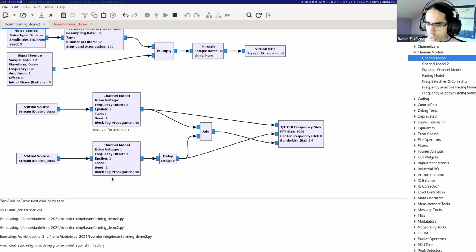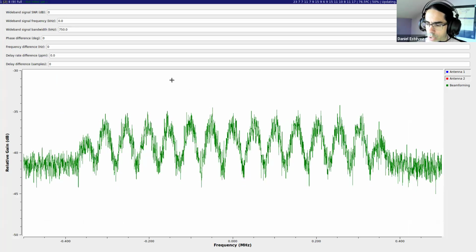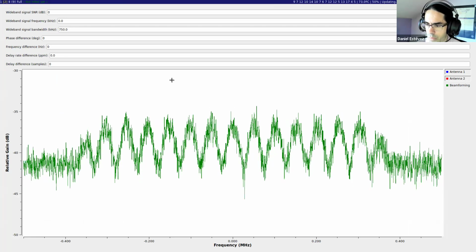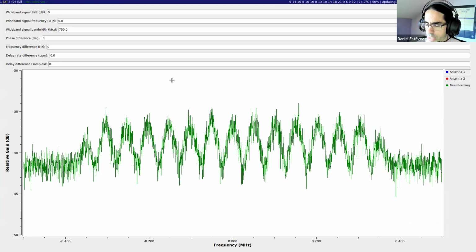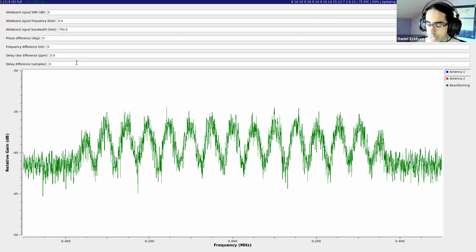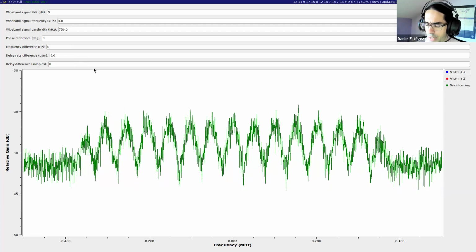So the atmosphere might also introduce a slight delay difference between the antennas because the atmosphere introduces a small delay on radio waves, which depends on things such as humidity and temperature. So you can imagine that these things can change and can be unpredictable. So because there are some unpredictable effects, I've mentioned the atmosphere, but also electronics, everything which has analog electronic components will introduce these effects, and often they are temperature dependent, so they will vary slightly over time.